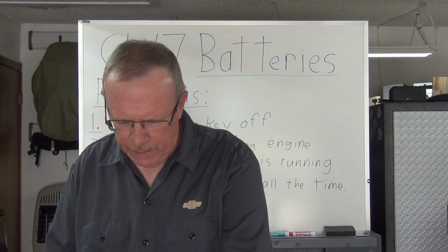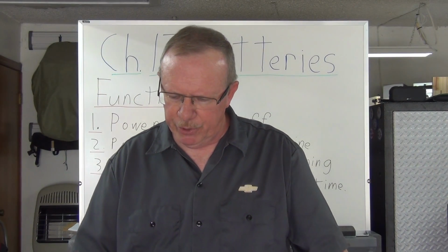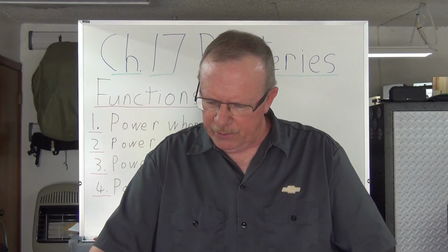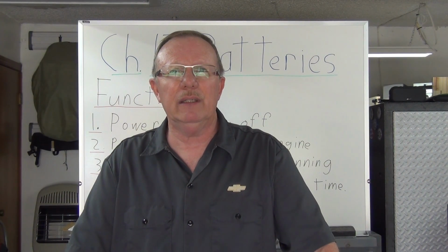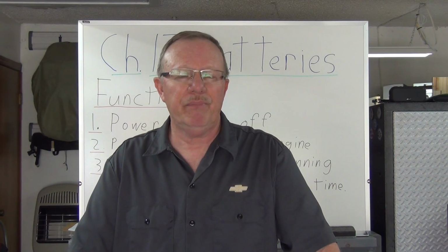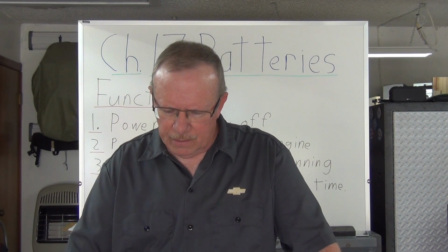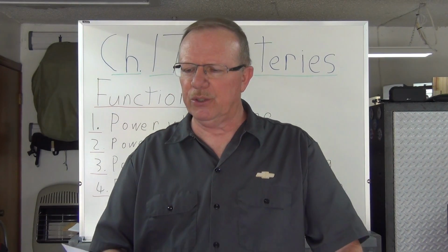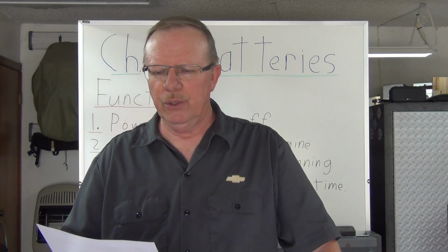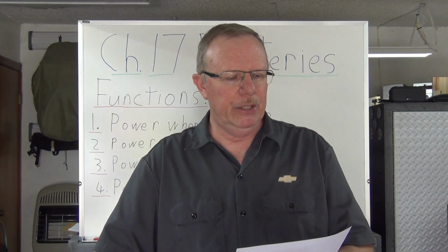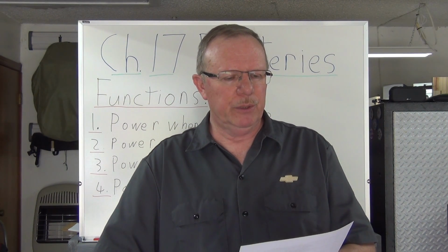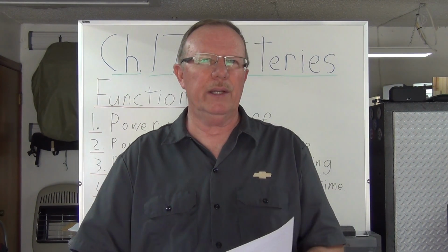Batteries. Wet and dry charge. So batteries can be produced as a wet charge, such as automotive batteries are today, or they can be a dry charge, such as a motorcycle battery, and so forth. So batteries in the cars today are wet. In other words, they have a liquid inside of them, sulfuric acid. Okay. Lead acid battery is filled with electrolyte and charged when it is built. During storage, a slow chemical reaction will cause a self-discharge, and periodic charging is required. Most batteries today are wet charged.